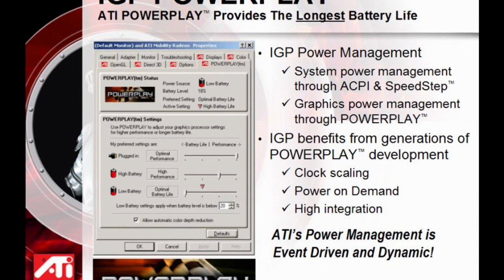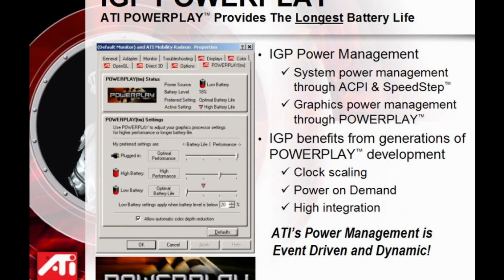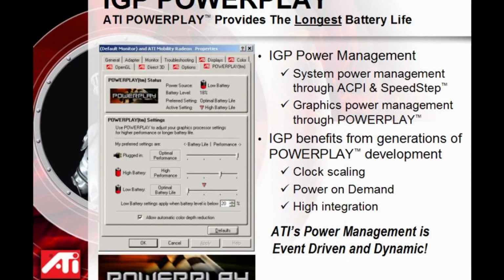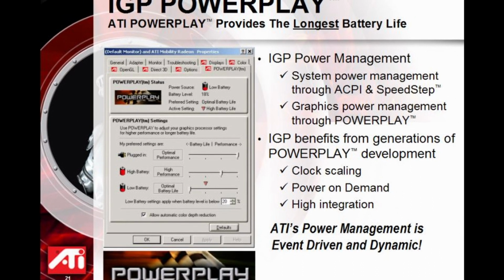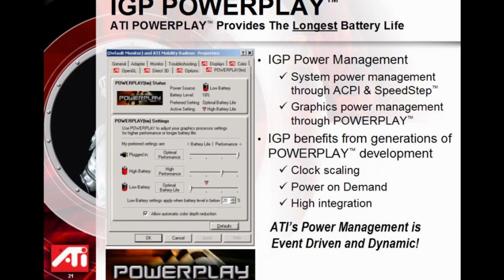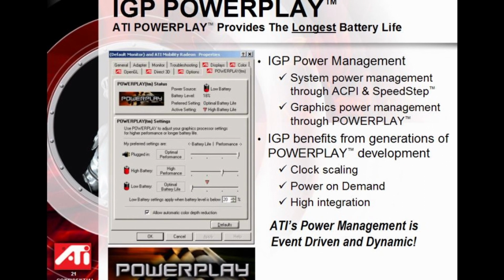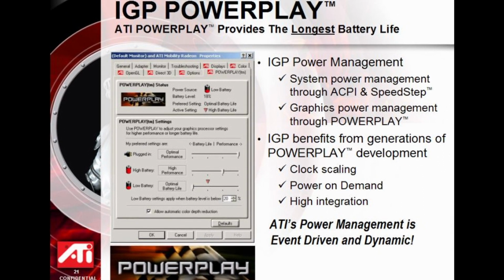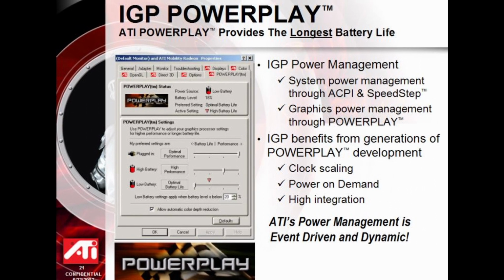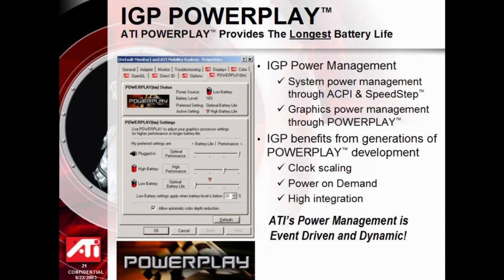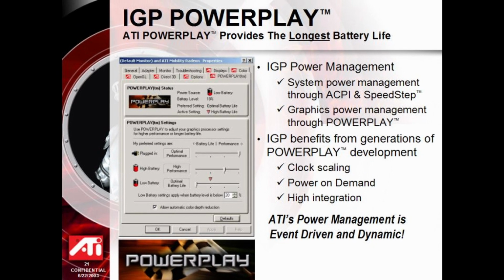In short, PowerPlay consisted of 3 fixed power states, each defined by a specific power, voltage, and frequency for the GPU. As the workload shifts from low to heavy and back, the power state adjusts accordingly. This ensures maximum performance when needed for heavy workloads and minimum power usage when there are no workloads at all.